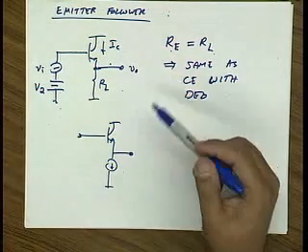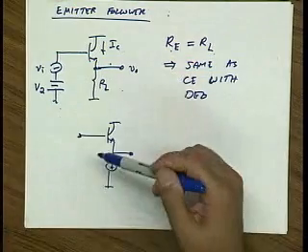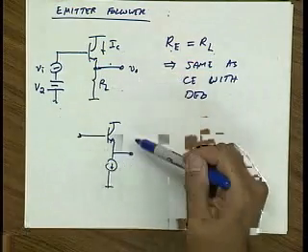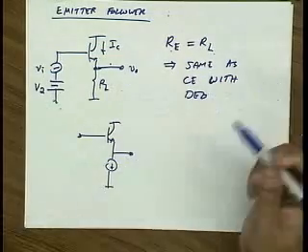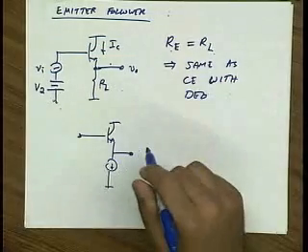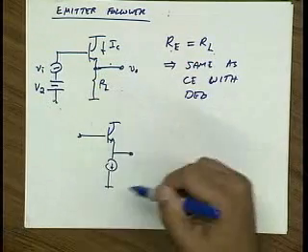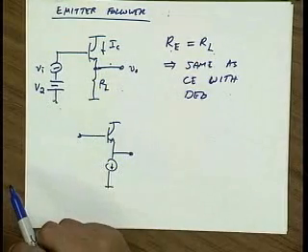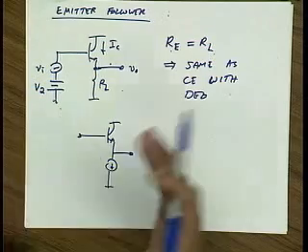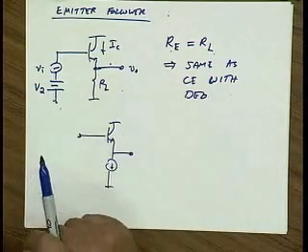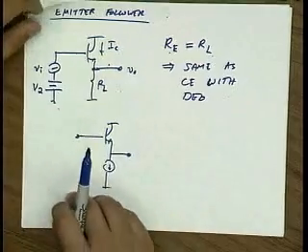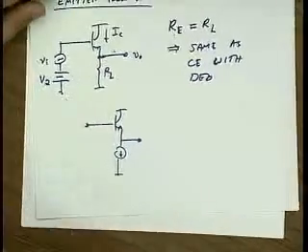And that's actually very useful because a lot of times in integrated circuits, we'll use a follower to drive an off-chip voltage, which is typically large. And so the swing is going to be quite large, and so it's good to take advantage of this nice linear stage. So it makes a very good driver, not only because it does the impedance transformation, but also because it's a low distortion driver. Okay? Questions?